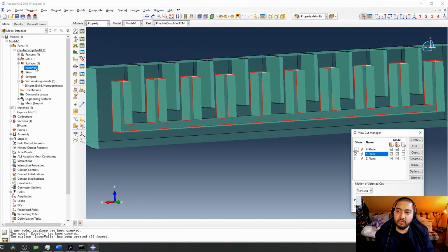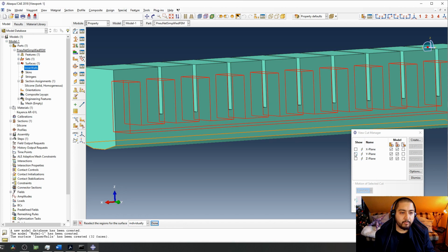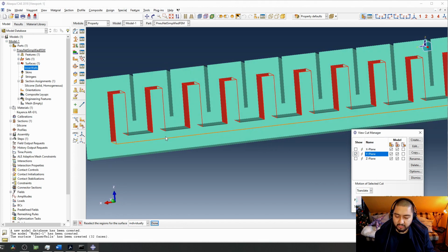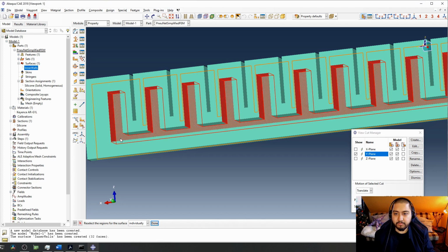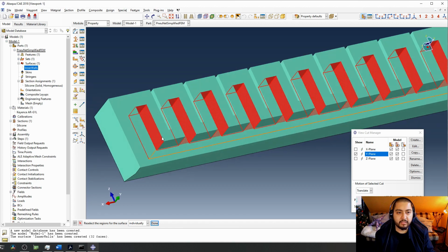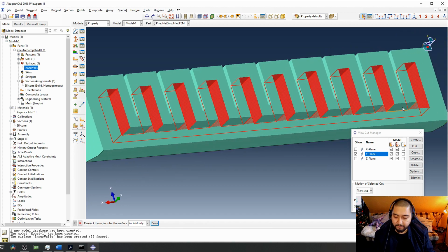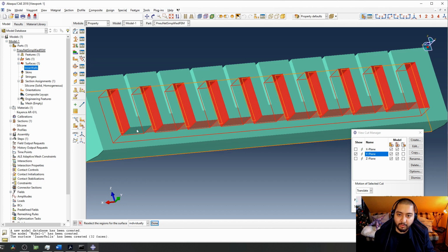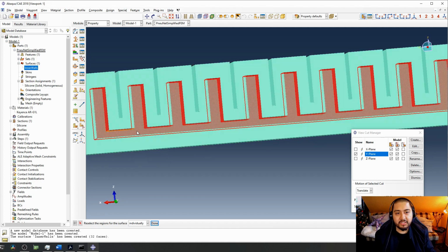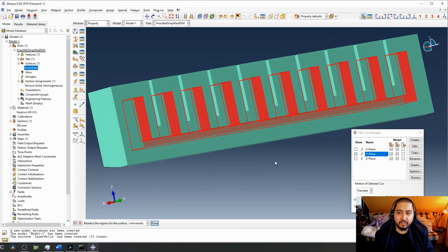So let's double click on inner walls again, and then press here again, and then we have the other side of the surfaces of the inner cavities. So we select this again, and I think that's all. No guys, we forgot this. As I said, we really need to take a look at which surfaces we need and are important for the simulation. So these are the upper walls inside the main channel. So I think it's already everything selected.